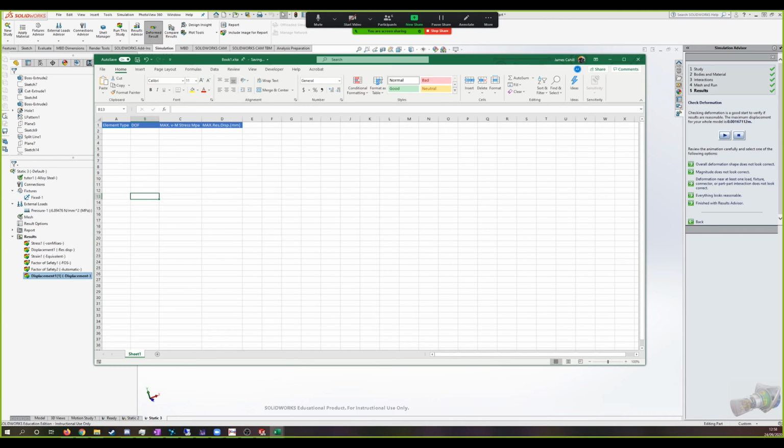Do you know the difference between a Tet 10 and a Tet 4? Tet 4 has 4 points. Tet 10 has 10 vertices. Yep. And then there's a difference in the way that they're solved too. Allow me to demonstrate. So this is a Tet 4 that we just did. It doesn't actually tell us anything. No, so by default you're doing Tet 10s.